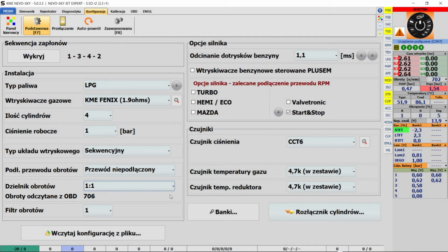Remember, in case of problems with the system calibration or bad operation, it is recommended to connect the RPM cable. Lack of accurate RPM readings may result in inaccurate or malfunctioning of certain features based on the values of rotation such as correction maps, the injection enrichment, cold start, etc.